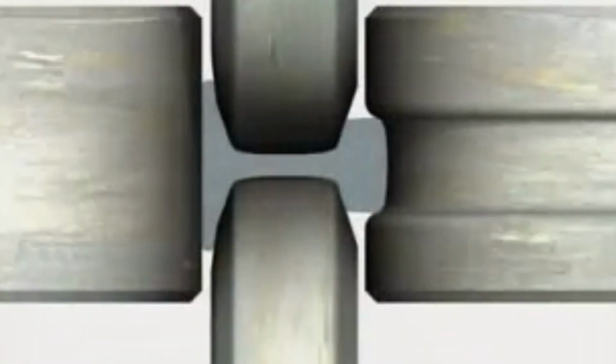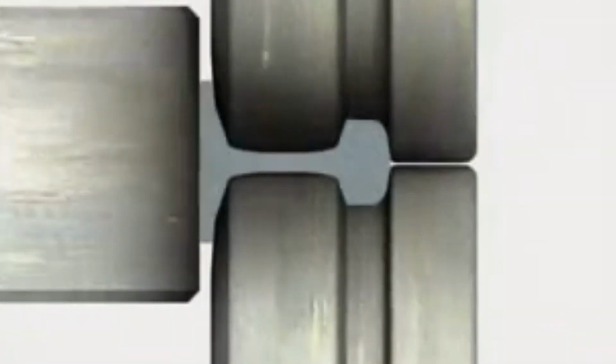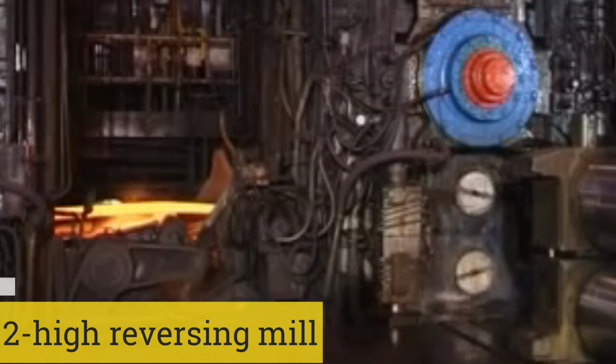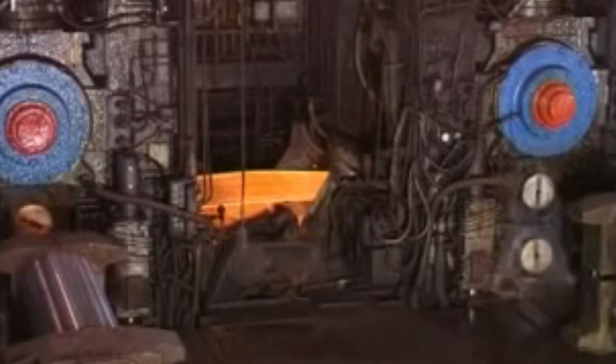This method of successive reductions slows down the process, and hence we have an alternate method which we call a 2-high reversing rolling mill, where the direction of rotation of the rolls is reversed after each pass.